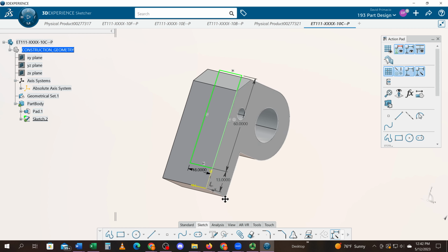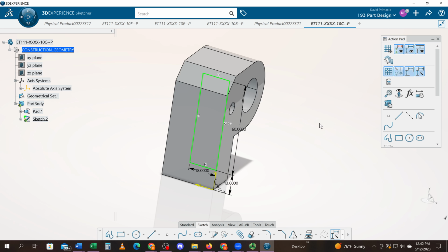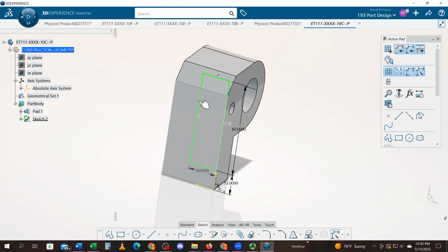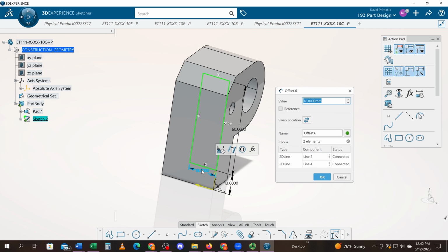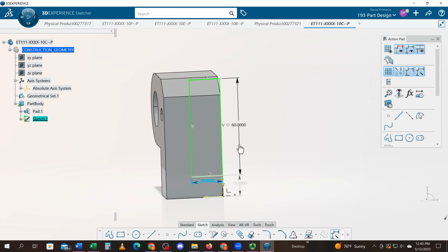Okay. So just looking at here in the ISO view, I want to remove this front chunk off and it is 35 minus the 16. So I got to remove 16 from that. So double click this. 35 minus 16 in my input field. Select OK. And I want to make sure that the part is higher. Okay, I'm going to do this intentionally wrong and show you.